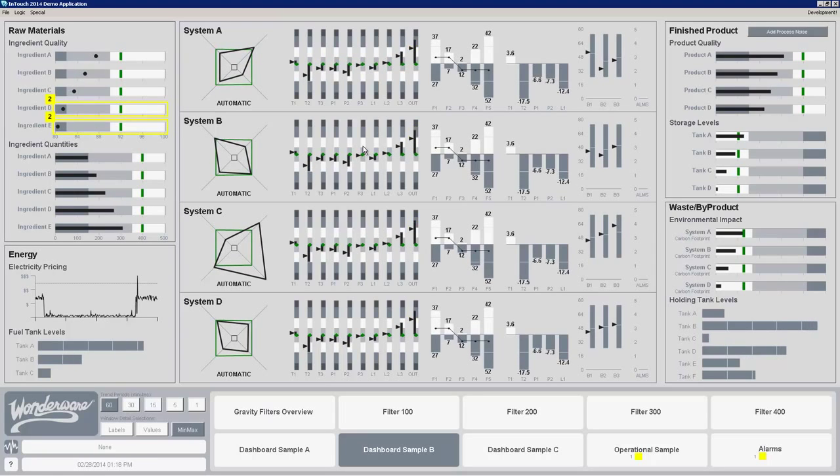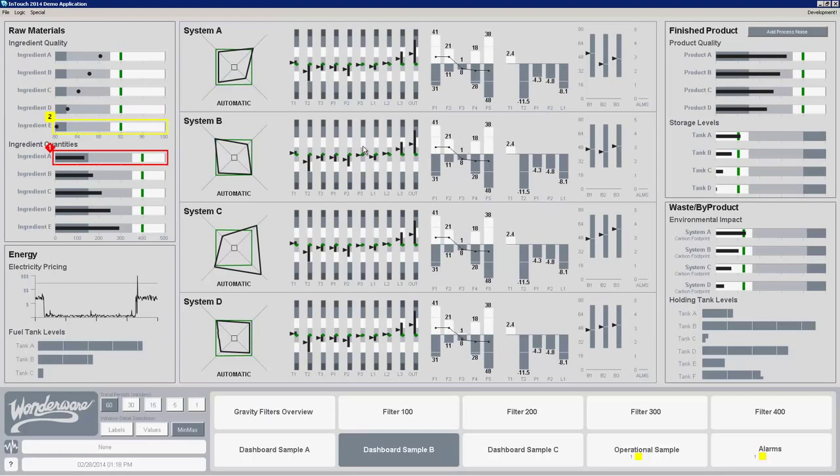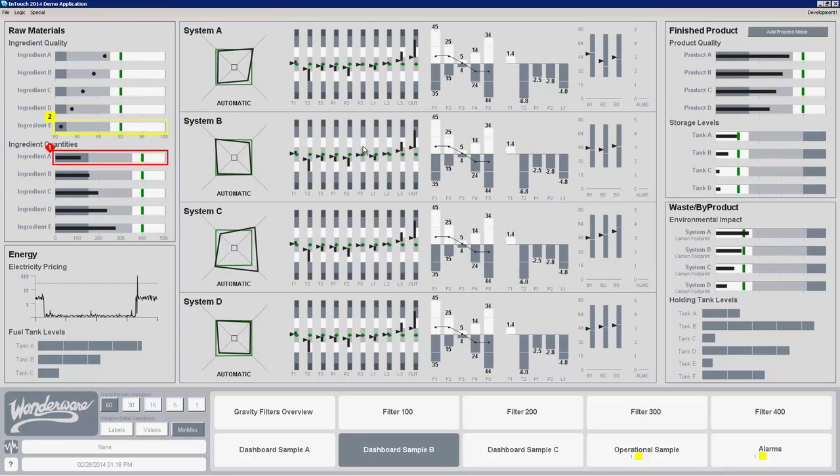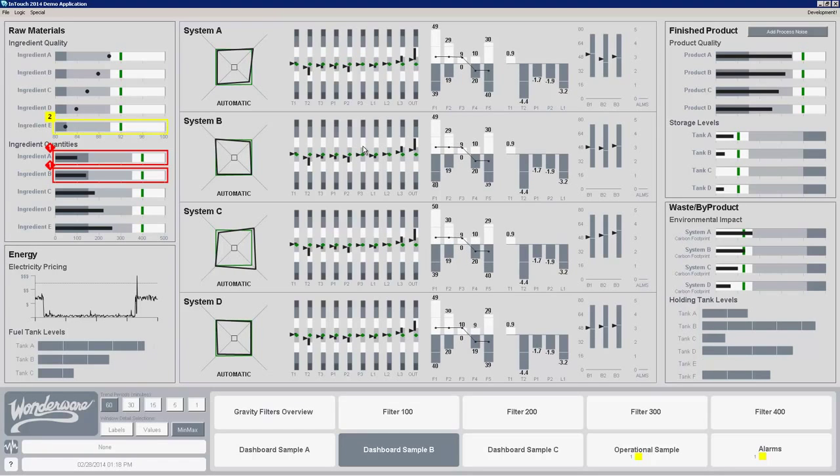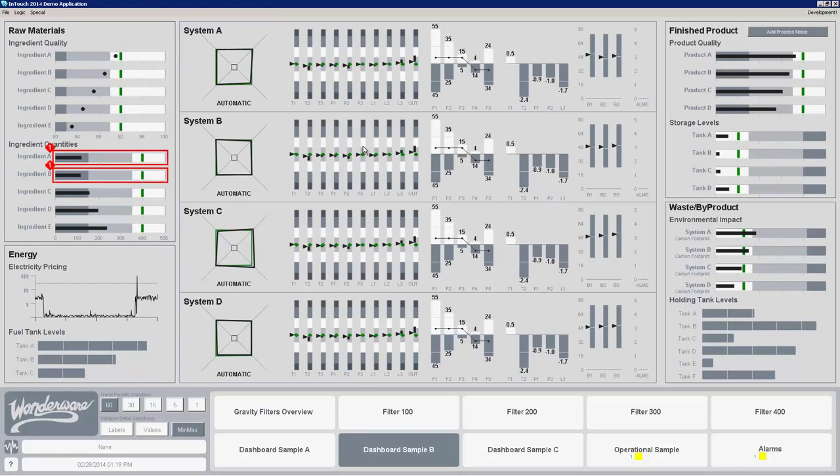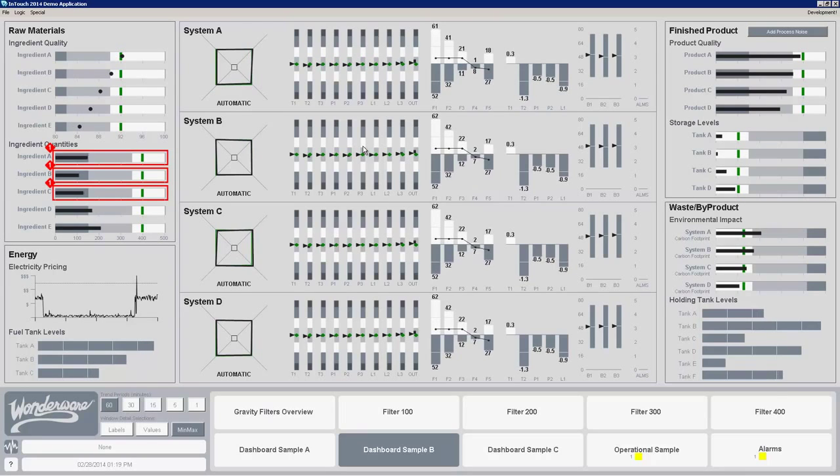But the intention here is to be able to, at a glance, understand: do I need to do something? Does action need to be taken? Some processes may be large enough to require multiple level 1 displays, and some of them may actually be small enough that you may even embed some actions on your level 1 displays. There aren't hard and fast rules here, and I would say that the story has not been finally written with regard to exactly what belongs in a level 1 display.